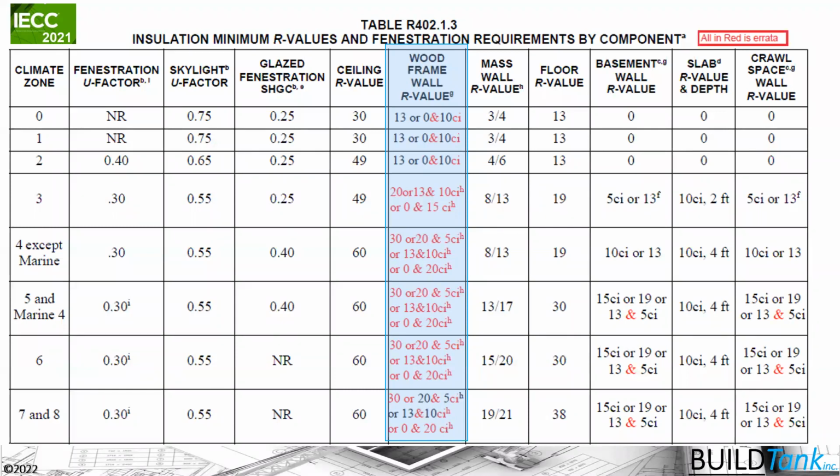And thinking about having less than, there are also some other requirements that have to be addressed in order to put in that R60 insulation in that attic, for example. And from that perspective, I'm thinking about raised heel trusses and other things that would be needed and required by the code in order to achieve that R60 in the attic. So we need to think about that as well from the perspective of how restrictive this pathway is.